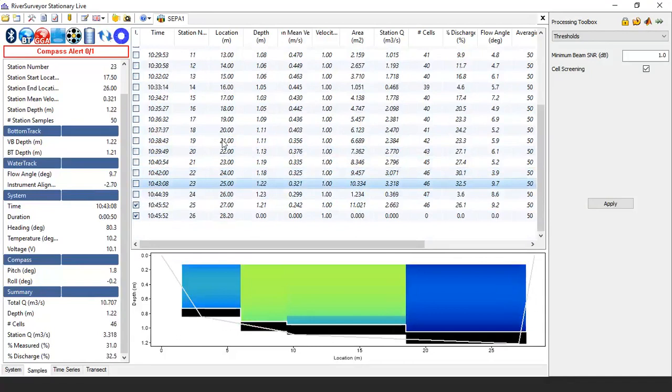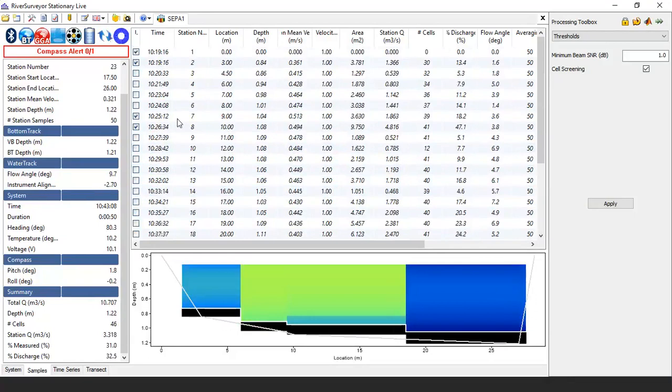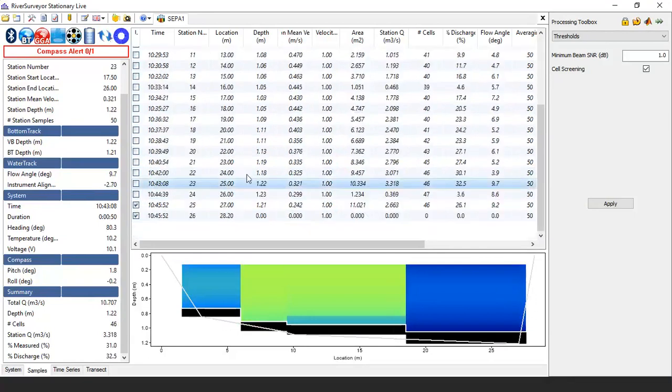Okay, so all I've left in there is 2 at the edge, so we get a better mean of those two. 2 at where the peak velocity was, and 2 again at the far edge, leaving those in, and we got 10.7. Okay, which is... I did work that out. It's 4.6% off of what putting them all in was. So then if you start adding in...